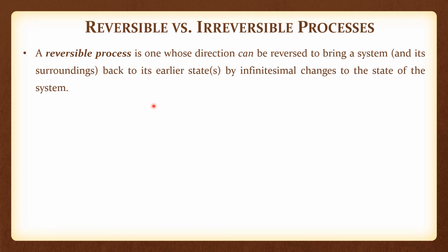This is something that is very commonly studied in thermodynamics, where you can have an idealized reversible set of paths which constitute a cycle. So you start from one state, you go to another state, and come back to the same original state. And when you have come back to the original state, then the temperature, pressure, entropy, energy, chemical potential, all those parameters, properties that we mentioned without formally defining all of them. Some of them we have defined, but many of them we have not, right? All those values are back to the same values for not only the system but the surroundings as well. And therefore, in order to effect this reversibility, typically what is stated is that the changes to the state of the system are done in an infinitesimal manner.